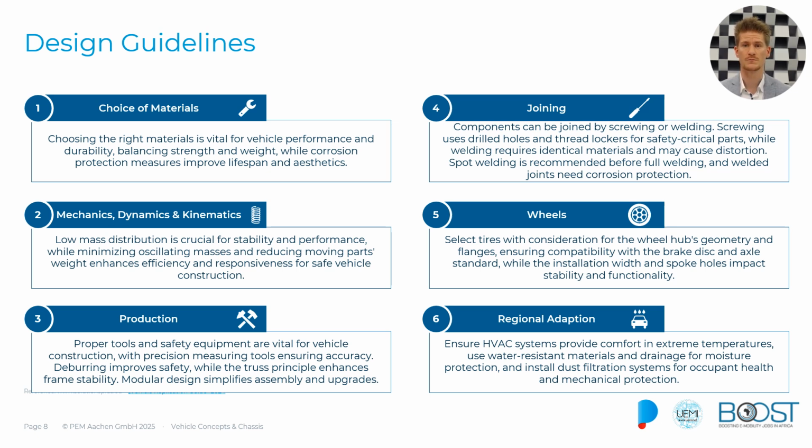If we come to joining or bonding, this is something we also want to take a look at. So joining has a huge impact during the production process and probably also beyond. So during the production, we could think of several things. For instance, adhesive bonding, which is very good because you have a low introduction of weight and it increases the strength and also the stiffness, but it takes time to harden. So during the time it hardens, you probably can't do anything with your vehicle in further production.